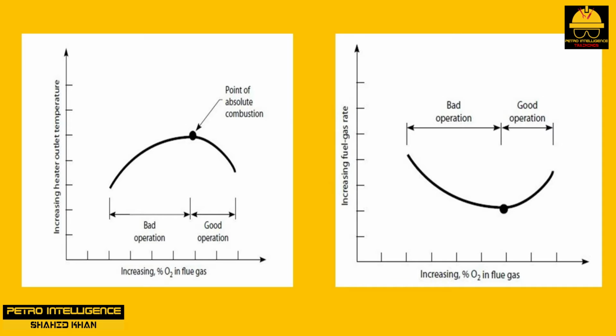If we have the furnace on automatic temperature control while we are not using enough combustion air, and if the control valve on the fuel gas then opens to allow more fuel to the burners in order to increase the furnace outlet temperature, the extra fuel will not burn efficiently. In fact, the extra fuel is likely to reduce the heater outlet temperature rather than increase it, as there is already a shortage of air, and it cannot burn properly and tends to cool the firebox.